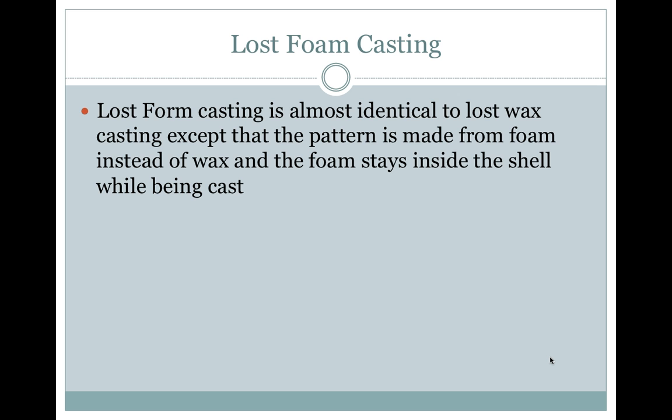Lost foam casting. Lost foam casting is also almost identical to lost wax casting, except that the pattern is made from foam instead of wax, and the foam stays inside the shell while being cast.